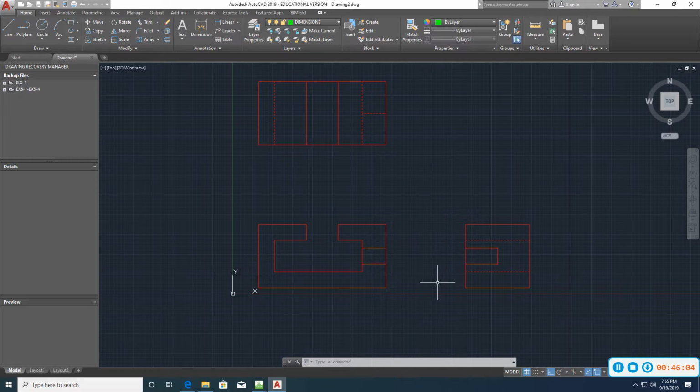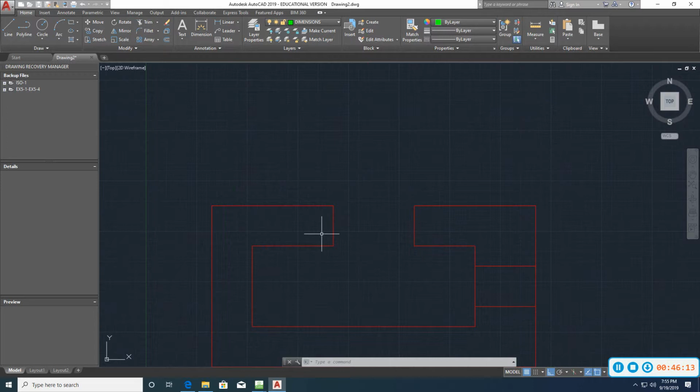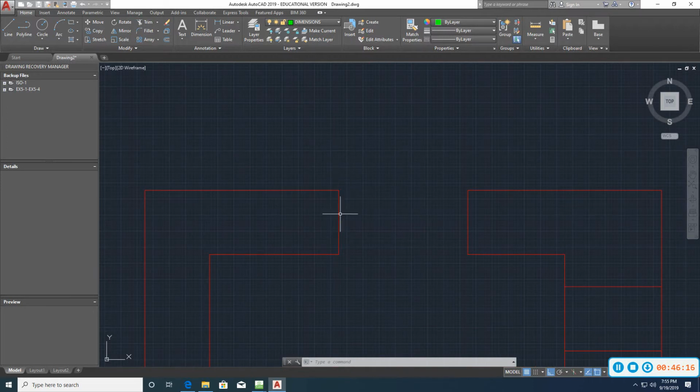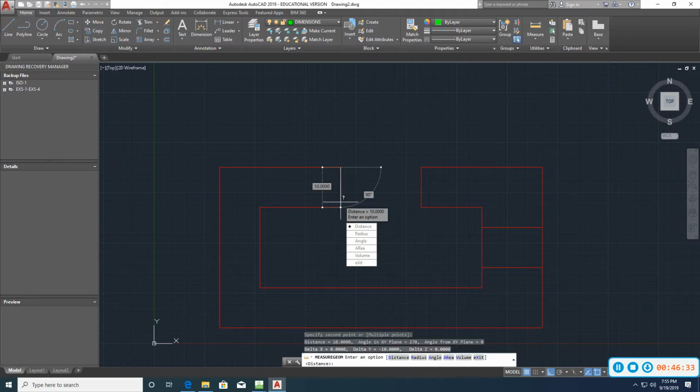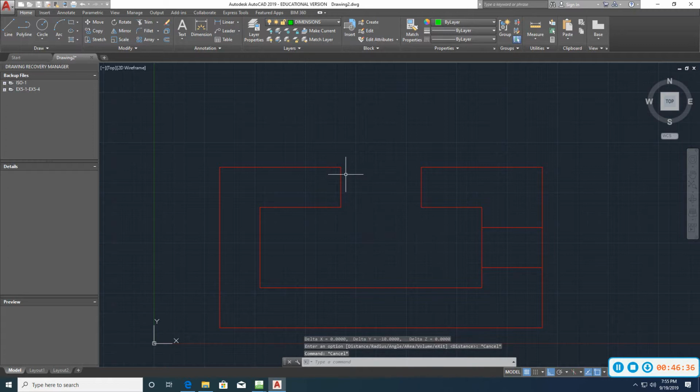So I'm looking at the scale. Mr. Morris is figuring, what size do I use here? Well, you have to look at this and think, well, this is 10. Isn't this 10 here? Or 15? It's 10, right? This distance from here to here is 10. All I have to do is go here and measure, right? It's 10. Well, if that's 10, maybe I should make my dim text, arrow size, offset, and extensions all the same. That's what I told you to do last night, or the night before.